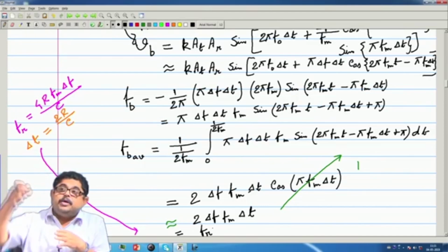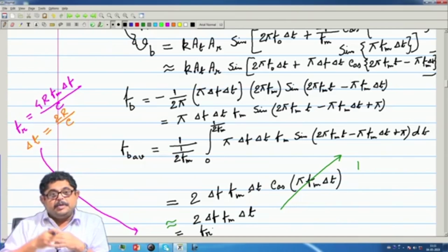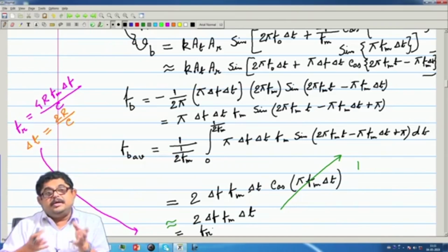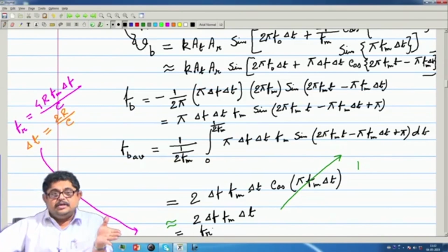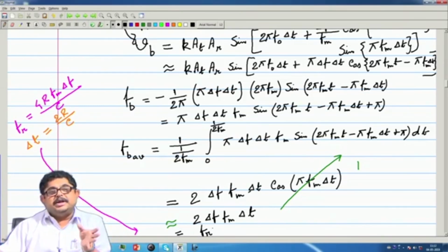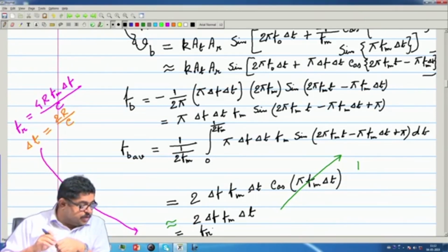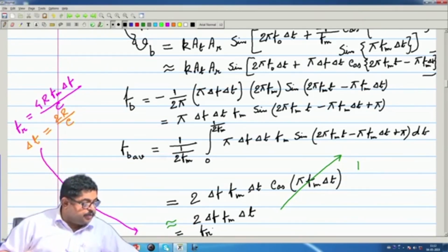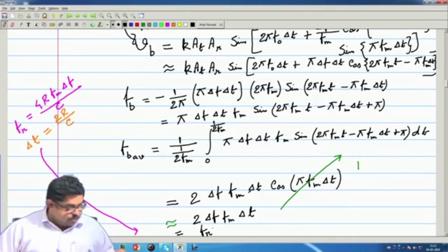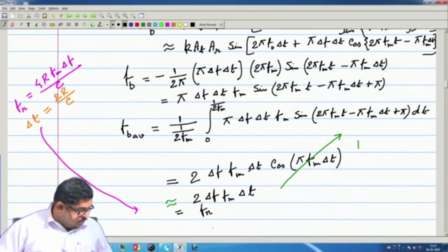Another problem with FMCW for aircraft detection is that the transmitter is high power, so the receiver and transmitter need a large amount of separation. In pulse radar that problem is not there, which is why pulse radar has become more compact, and nowadays it can give you much more range compared to FMCW. So, we will see the block diagram of this FMCW radar next.